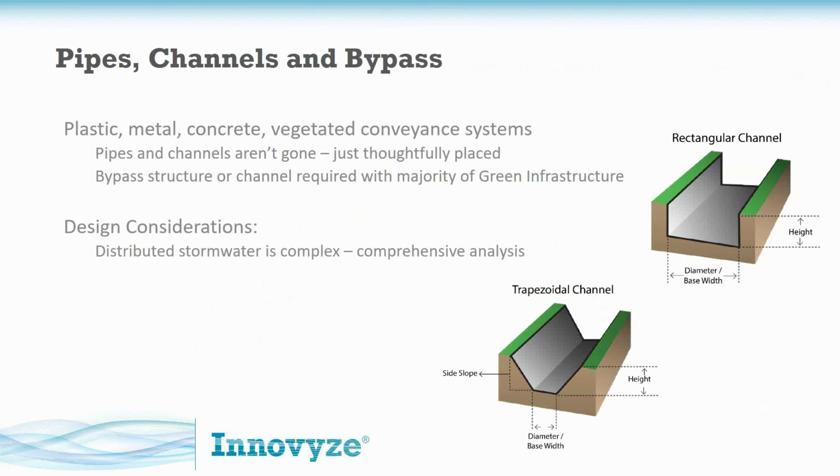It's not enough to say, all right, how big should this pipe be? Done. No, you've got to see how the flow and the timing throughout the network, throughout these ponds and rain gardens, impact each other, okay? Because they will. That's basic pipe sizing versus really integrated hydraulic design.